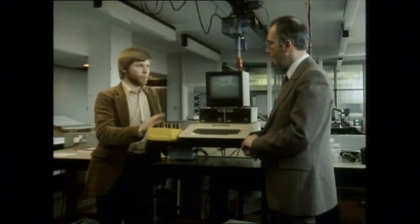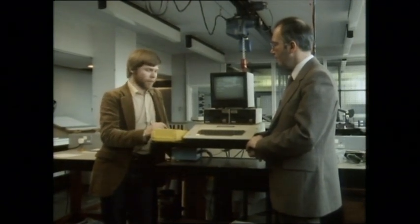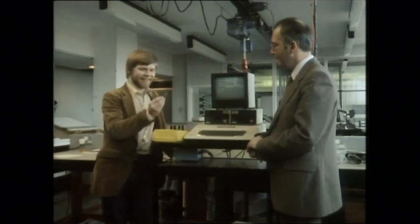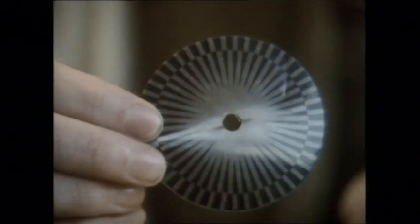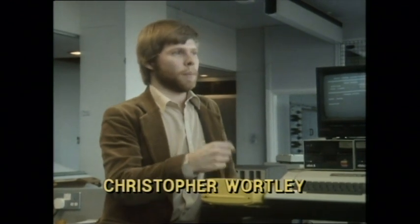On the 2 movements of the hoist, the vertical and horizontal, there are optical encoders. Now, what's an optical encoder and how does it work? Well, inside each encoder is a disc similar to that. This has little black markers on it. As the hoist moves in either direction, the disc rotates and interrupts a light beam, which sends pulses back to the computer at high speed. These can then be counted up by the computer, so it can keep a continual reference in space of where the hoist is.